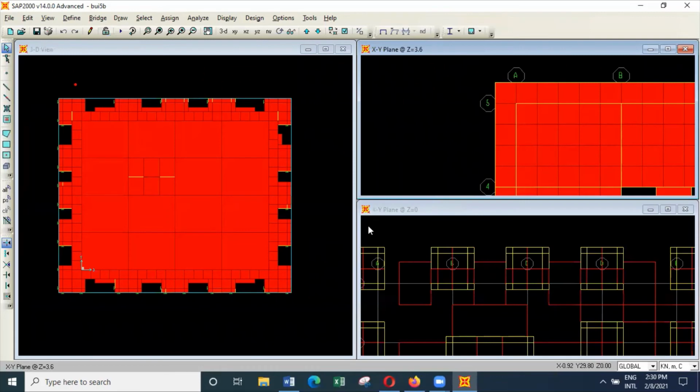So you can see that doing this kind of analysis, you can actually get the bending moments, shear forces, and axial forces acting on the columns, the piles, and also we can get the loads on the pile caps and transfer plates. In addition to that, we can get the natural period of vibration of the structure that can be used for calculation of wind-induced accelerations.